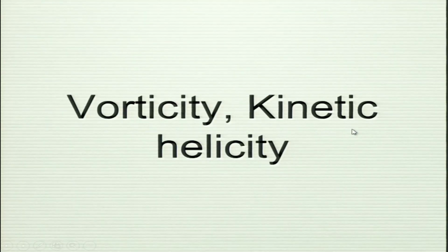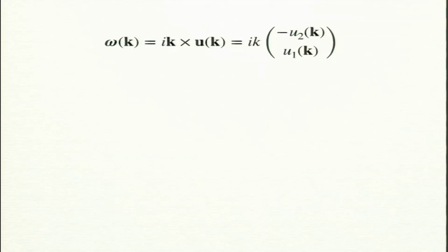Okay. So, what about vorticity? You can write vorticity in terms of u1 and u2. The vorticity vector is i k cross uk, so you can take a cross product. Now I want to write k as k e3. You have to use the Craya-Herring basis, do not use x, y, z. So, k has only a component along e3, and u has components u1 e1 plus u2 e2.